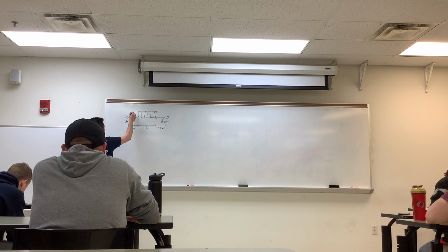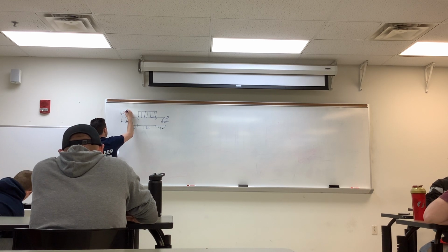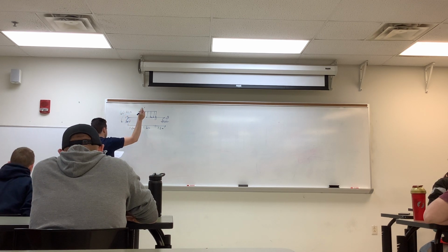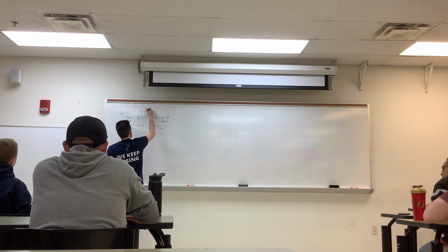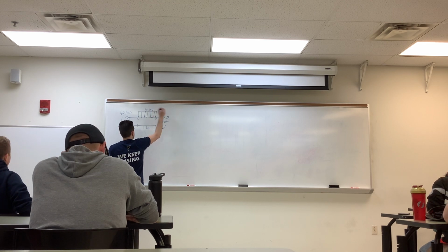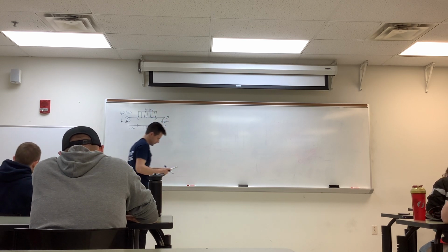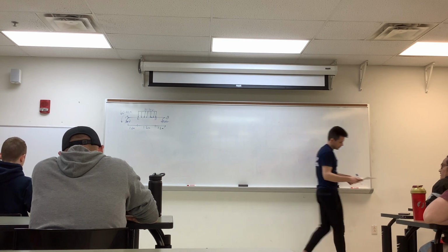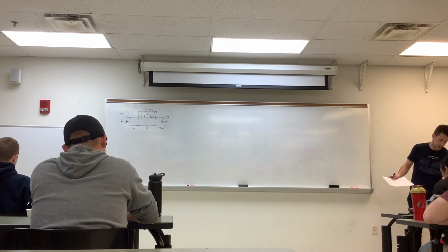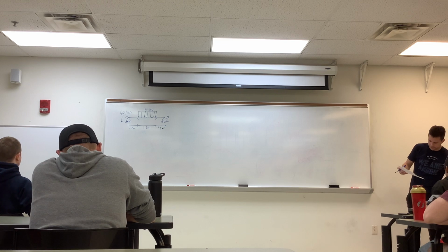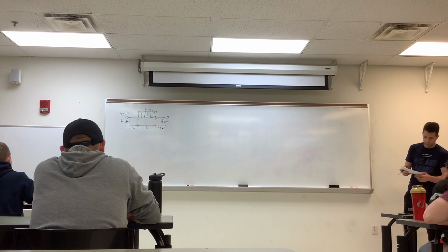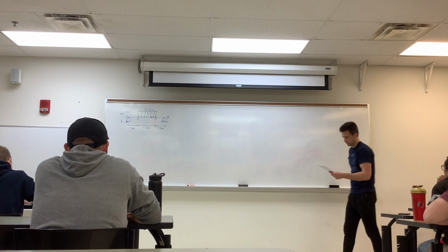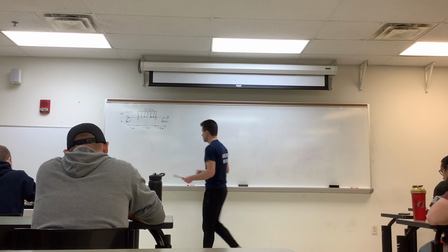And then also, at point A, there's a 60 kilonewton meter force going counterclockwise, and then this distributed load is 80 kilonewtons per meter. So all you guys are going to need to do for this one is just solve for the shear moment diagram. I want to see your entire process behind it and each of the steps accordingly. So starting off, we're going to find our reactions.